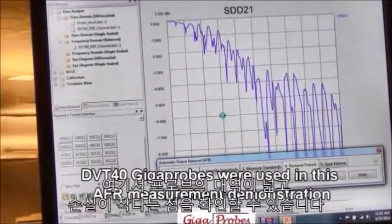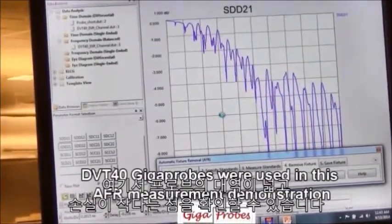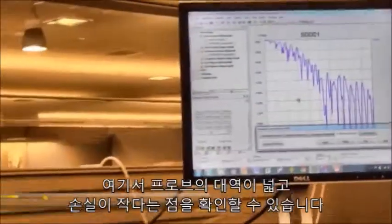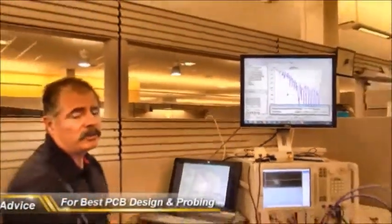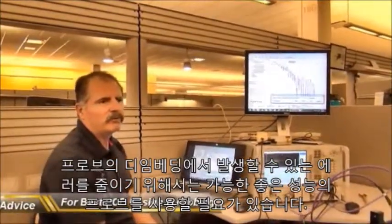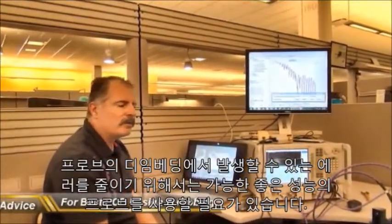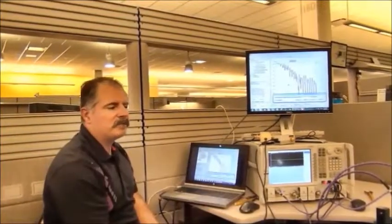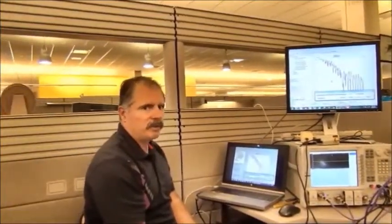So it's good to use the best quality probes you can. You don't want to make the mistake of saying, well, I'm going to de-embed the probes anyway, so it really doesn't matter how good the probes are. That doesn't really hold at all. You want to get the best PCB material, you want to get the best probes, you want to be able to really get the best quality of signal integrity measurement before any of this error correction happens.